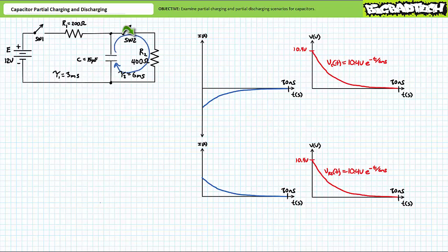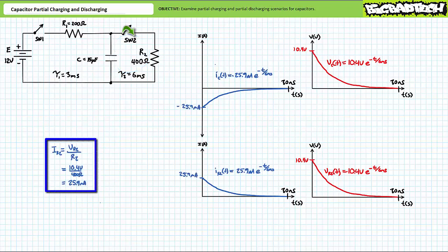During the discharge phase, current through the capacitor, Ic of t, experiences a momentary spike and then drops. When discharging, current leaves the capacitor. This reversal of current flow must necessarily be accounted for with the use of a negative sign. All current leaving the discharging capacitor must travel through the discharge path provided by R2. No prior convention has been established for R2, and as such, we're free to assume incoming current travels top to bottom.